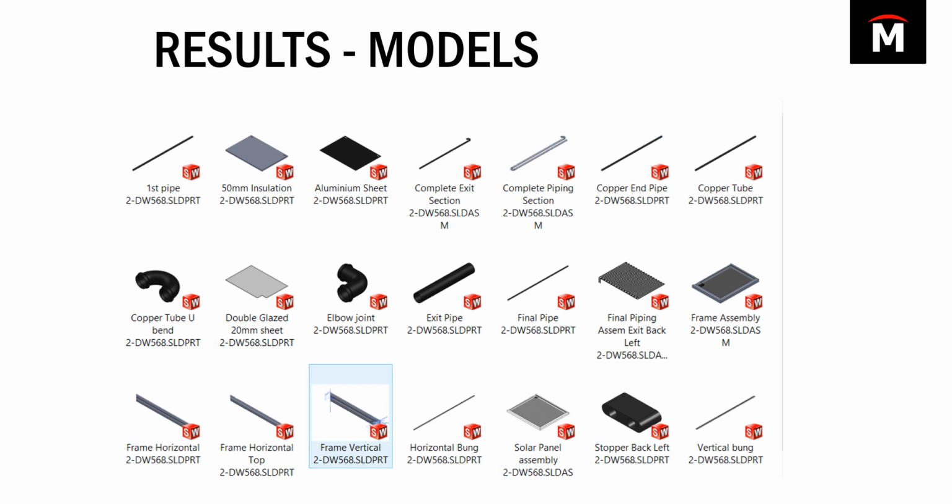And so really what it starts with is all of your SOLIDWORKS parts and assemblies. What Driveworks does is it takes all the information on that form that you filled out and it starts to drive it into things like dimensions, reference geometry, custom properties. It opens up each one of those model files and it starts to change the parameters that you've specified.